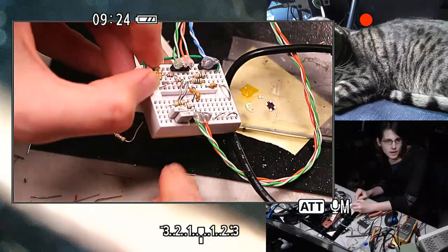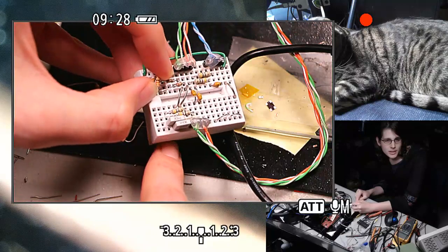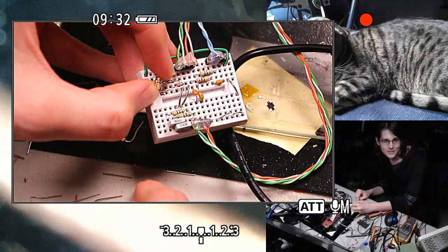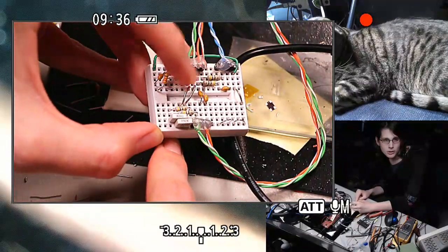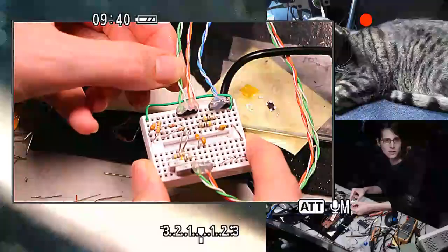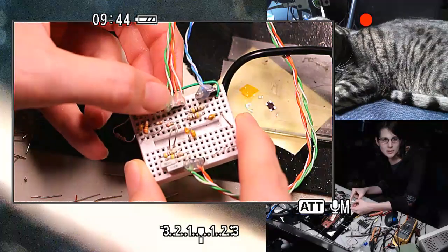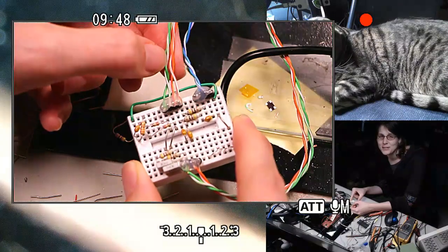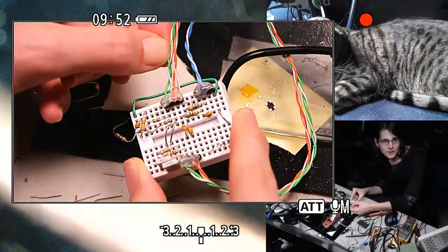And I still am not quite sure what the failure is in this particular circuit because it's not completely dead. I was getting occasional packets through, but it's really unreliable. And based on how good the signal looks on the scope going this direction, I think the problem is on the receive side of the ENC28J60. So it's possible that whatever receiver it's using isn't necessarily the greatest differential amplifier, and it's just not picking up a clean signal.